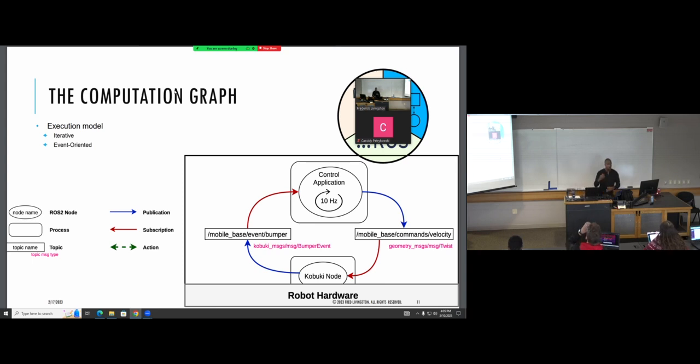There is a ROS core, so you have a centralized server somewhere. It could be running on your machine or on the actual robot, and both computers will connect to that. So you need to know the IP address of that, and then they can connect to each other. For example, for the ground robot, we'll need to know the IP address of this laptop, or the laptop needs to know the address of that, and then I can make a connection.